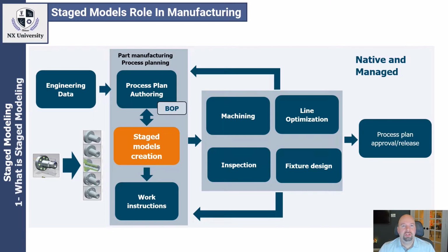So looking at our first topic here, stage models' role in manufacturing. If we look at the diagram down below, we can see in bright orange there the word stage model creation. This is the process of creating from your finished production part the stages of manufacturing going back in time. There are other options as well. You can do a hybrid design approach here using a finished production part and an as-cast part, and then creating the manufacturing stages in between.